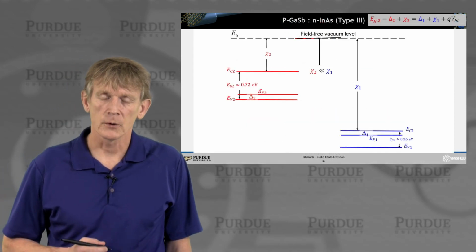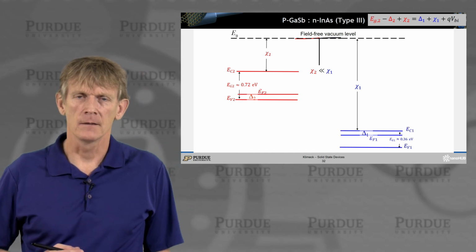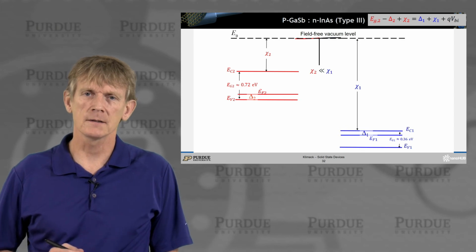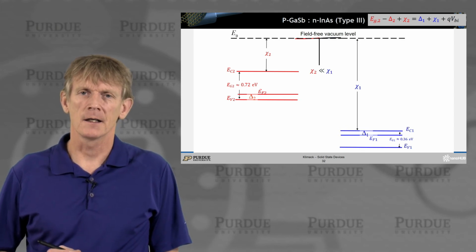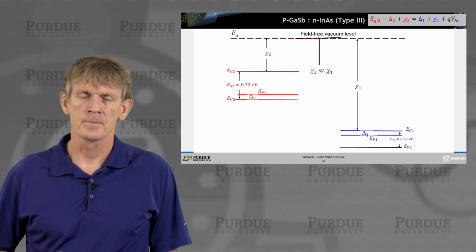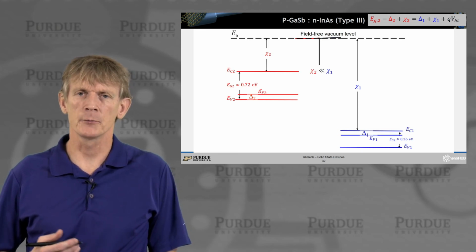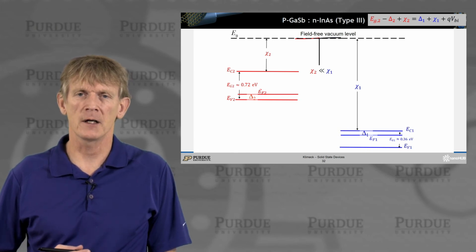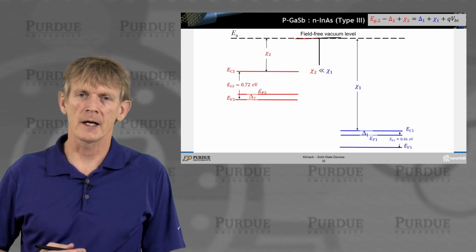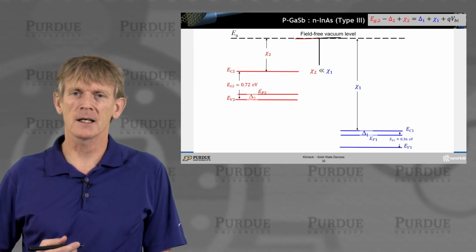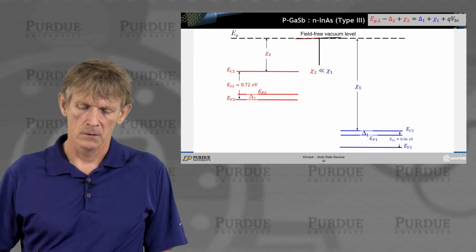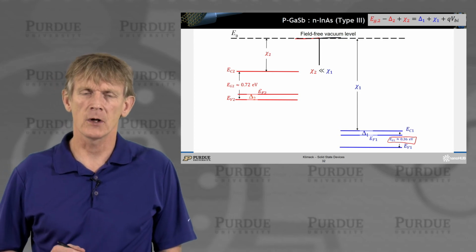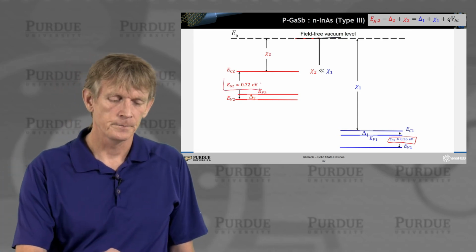All right, now we're getting to a type 3 heterostructure. Now, this one looks quite interesting, and I'm starting from a slightly different point of view. I'm not starting from the Fermi level being flat throughout. I'm imagining that I have these two materials far apart from each other, and I want to show you the dramatic difference in these materials. The band gaps, ballpark, are the same. Well, they're not quite the same. This is 0.36 on the right-hand side. That's indium arsenide. Very small band gap.